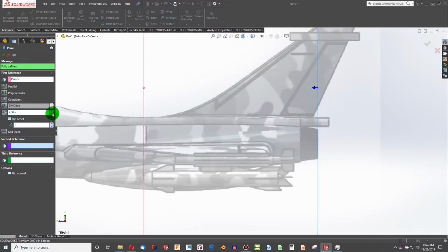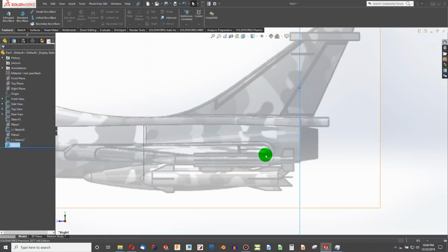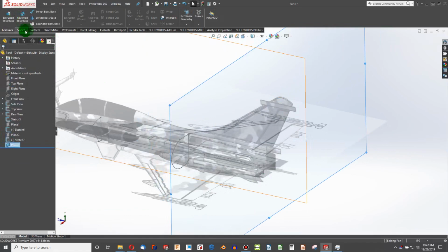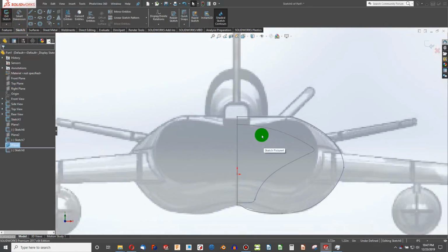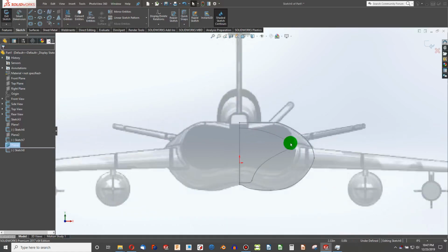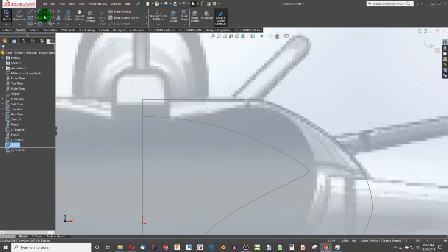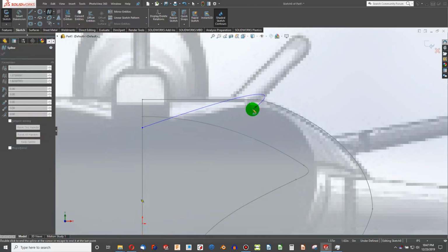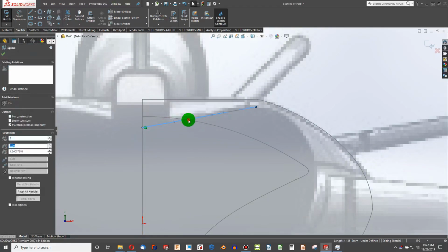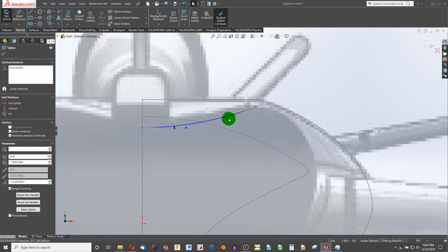I'll take the body right back before this nozzle, right there. So we'll select that, and we'll sketch. So I want to take this end profile of my body, and I've already got my rear view selected. So I'll grab a spline, and I can make it coincident because this references the center. We're going to go from here to here. I'm going to say horizontal, horizontal.